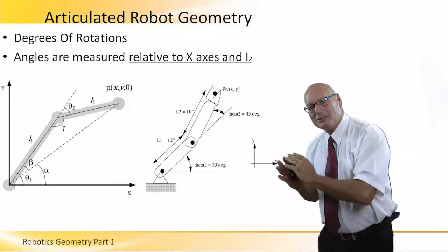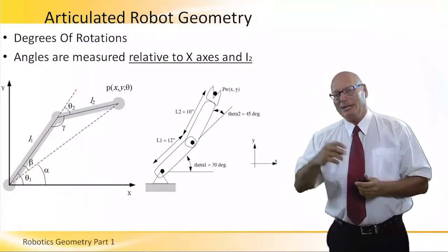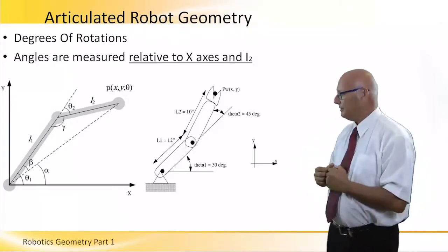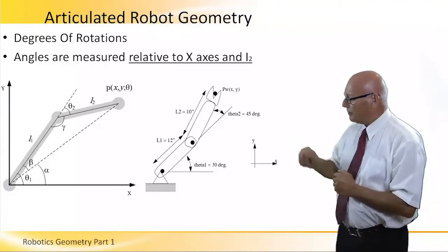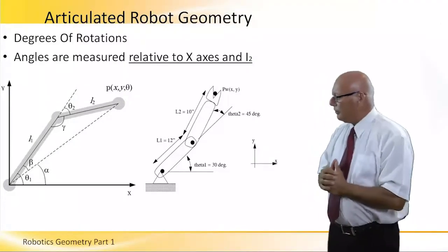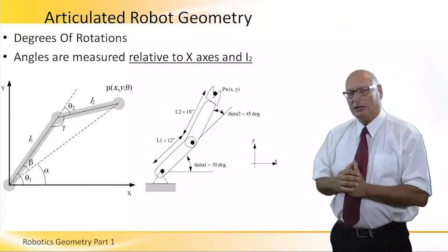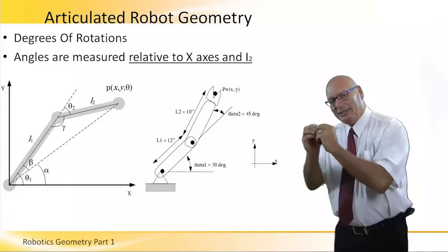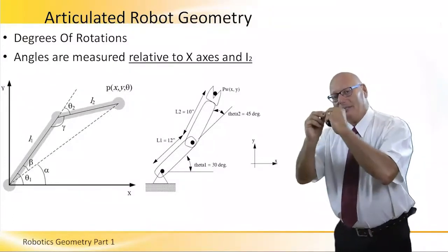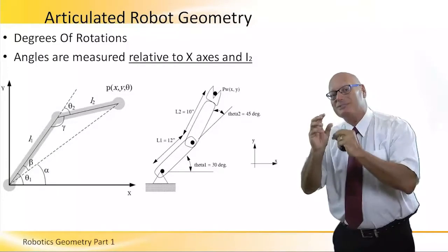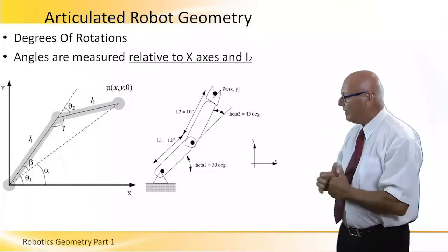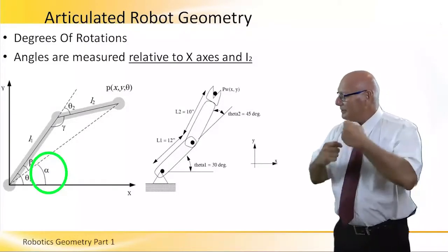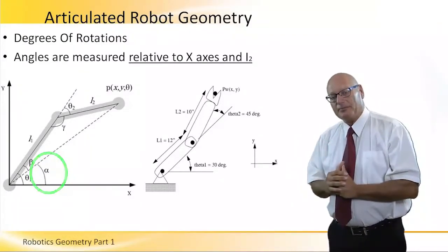And this is a somewhat different relation of how we define the angle. Look at the point on the left part of the picture. We see the point where the gripper is, which is x, y, and theta. And the angle theta of the starting position of the gripper itself is alpha. And alpha is basically theta 1 minus beta.